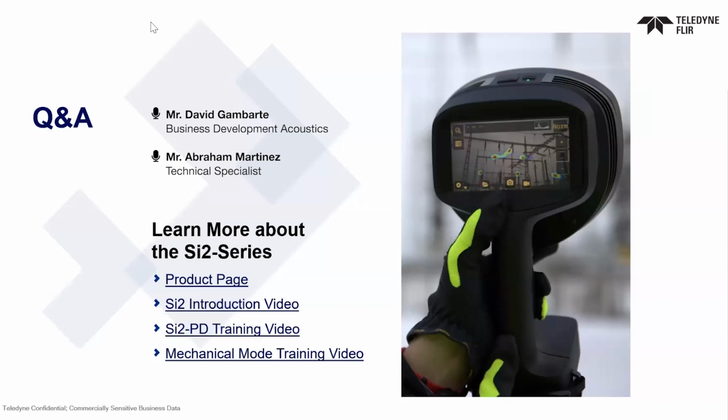Basically, the user needs to select the type of gas, and based on that selection, the camera will store this value and retrieve the information. We expect the user to know the gas that is in the pipe or in the component where they are finding the leak. They just need to introduce the gas type or the gas name, and then the camera will automatically do the calculations afterwards.